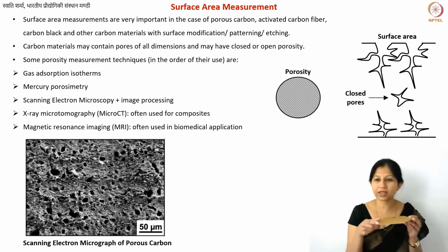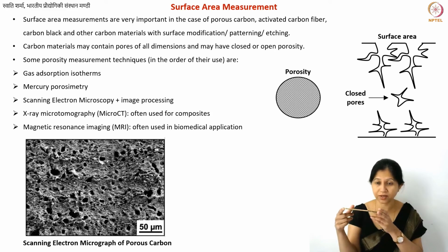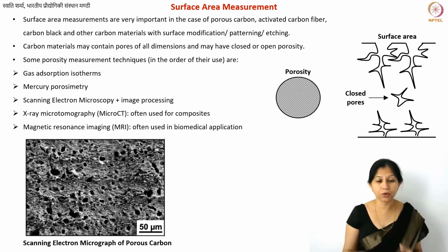Now if I want to see the cross section, the film is very thin. So I want to see the cross section of this very thin film. Let's say it's 50 micrometer. Now what I can do is, SEM machines typically allow me to tilt my sample a little bit, but only to a certain degree. Your sample might also be very fragile, and it depends also on how nicely cut your edges are.